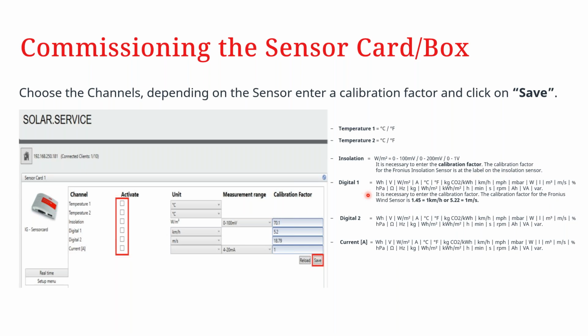Good. So next up is the digital input and the current-based input. It comes in as a very, very flexible channel, because they are freely configurable and there are so many quantities that you can actually measure in this case. You have them all represented in their respective SI units. Just going through a few, you can measure energy density, voltage, irradiance, temperature.